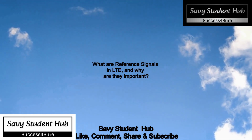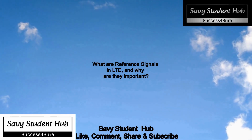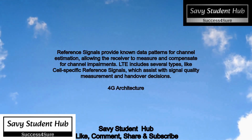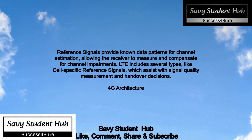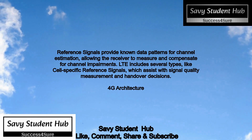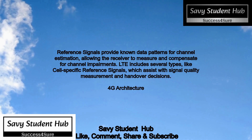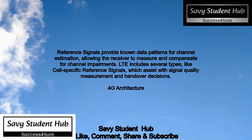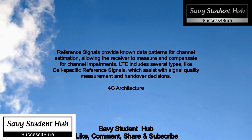What are reference signals in LTE, and why are they important? Reference signals provide known data patterns for channel estimation, allowing the receiver to measure and compensate for channel impairments. LTE includes several types, like cell-specific reference signals, which assist with signal quality measurement and handover decisions.